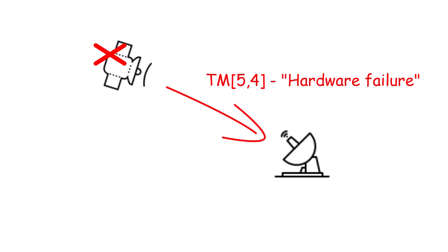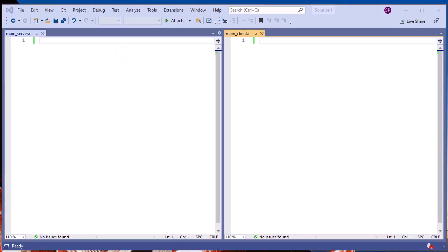That's about it for the introduction into PUS Service 5. And now let's jump to the live demo. So in this demo we'll send TM51 with PUSopen from one application to another via socket, but in your application very probably you will send the message through the data bus between the subsystems on board, or from the test PC to the satellite, or from the satellite to the ground station and so on.